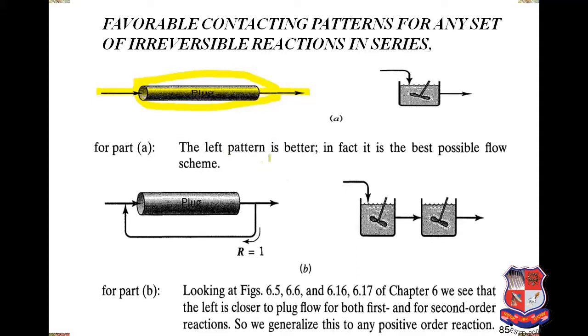More accurately, we are saying it for order greater than 1. Consider a plug flow pattern with some recycle. As the recycle ratio increases, it converts into a mixed flow reactor, the MFR. And you know that instead of a single CSTR, multiple CSTRs in series give the equivalent of one PFR.